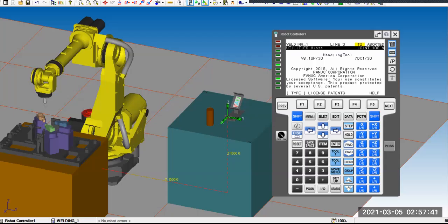Let's look here with HandlingPRO. We have two boxes in this robot cell. One is the brown box, the other one I call the blue box, right? There are different features on top of the box, and it's like a machine, or what we call a workspace. We already worked on different programs, inside tree, outside tree, and line program, from this brown box. You also did some programming with the blue box. So a user frame is basically when you want to move the reference starting point from the robot base 0, 0, 0 to the boxes.